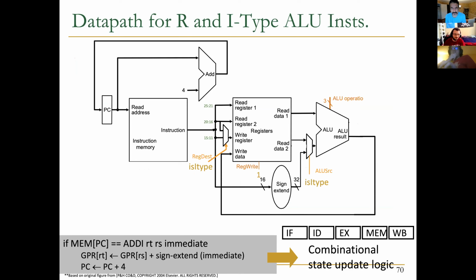But is there anything, in terms of the example that we discussed here, adding an ALU? Are there any other elements that you could remove or add here that give you the same semantic but different performance? Any guess should be fine. Could you not come up with a way to make the ALU also do the program counter function, the +4 to the program counter? That's right.